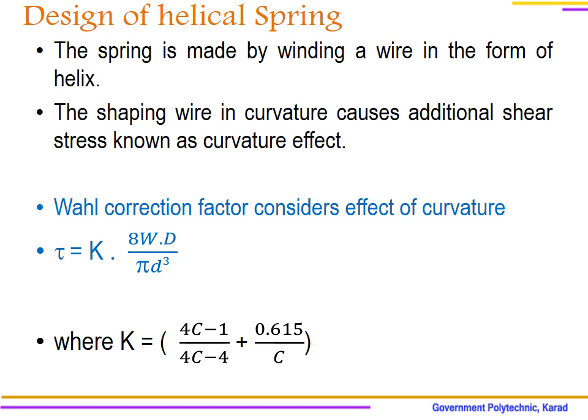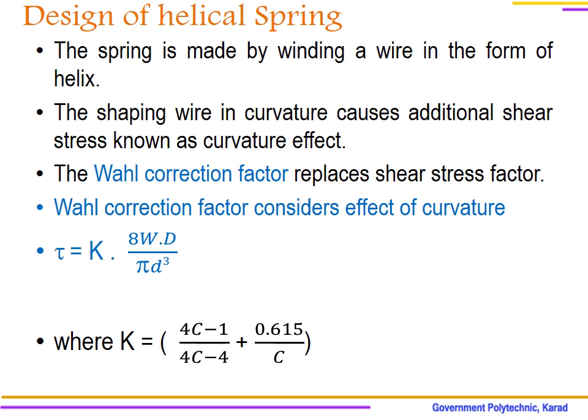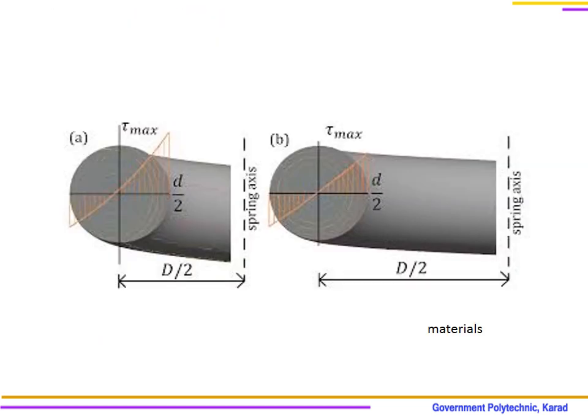In case of small springs, it is necessary to consider the effect of curvature. So we have to use this Wahl's correction factor, especially for small springs. So it is replacing the shear stress. See here, a small and a large spring is shown.